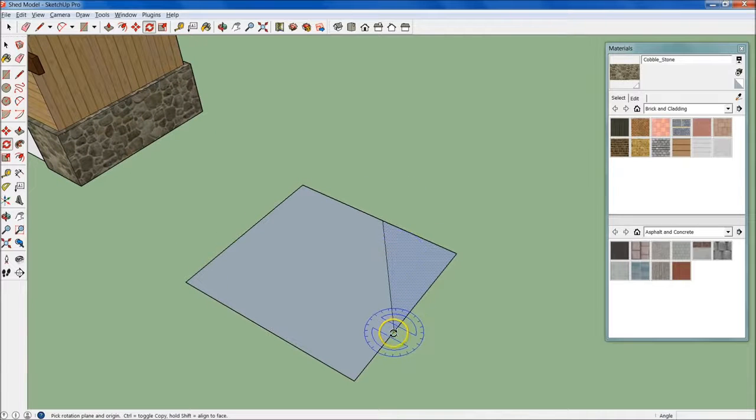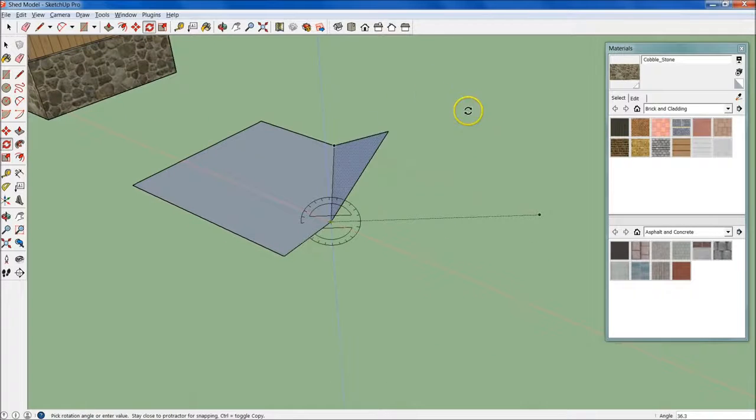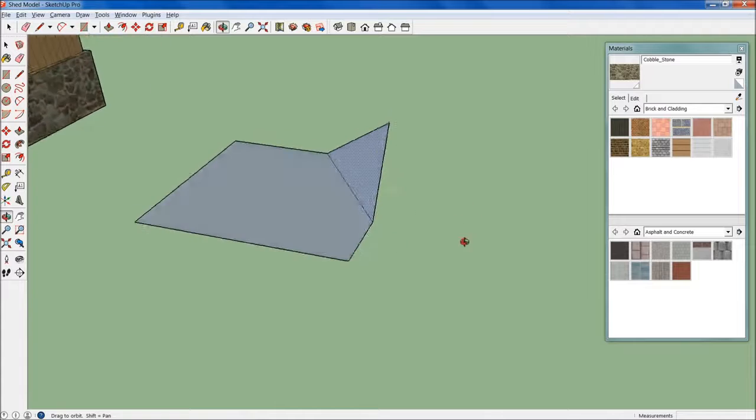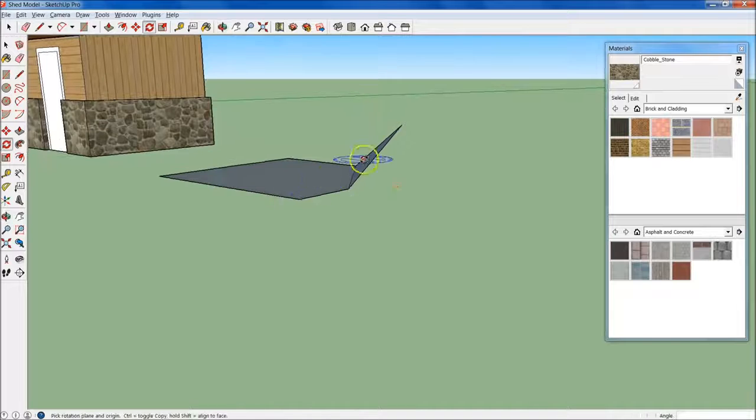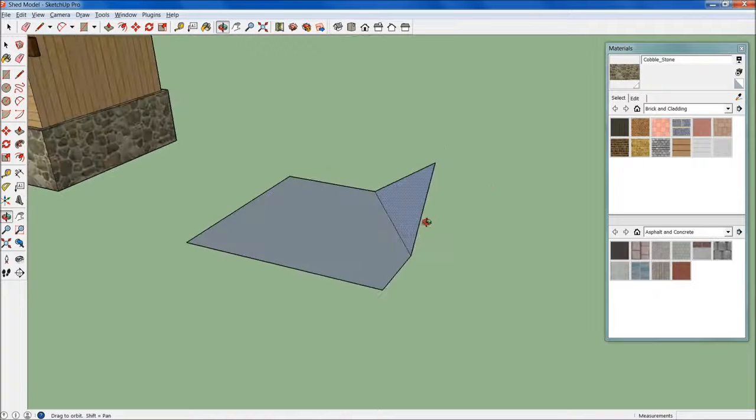So how you do that is you want to click on this point right here and hold down on your mouse. So hold down on it, come up right there, release on this point, and then you can come out here to choose your handle. This is if there's a reference point out here that you want to click to. I'm just going to click from right here because it's lined up with that corner there. And then you rotate from there. And you can set your angle right there at the bottom on the right. You'll see I can set my angle to 45 degrees. But yeah, now you have that awesome fold right there instead of using the basic 3 axes.